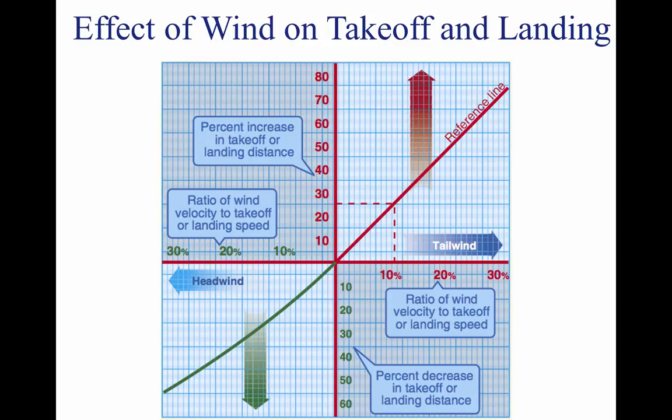The effect of pressure altitude and ambient temperature is to define density altitude and its effect on landing performance. An increase in density altitude increases the landing speed, but does not alter the net retarding force. Thus, the aircraft at altitude lands at the same indicated airspeed as at sea level, but because of the reduced density, the true airspeed is greater. The most critical conditions of landing performance are combinations of high gross weight, high density altitude, and unfavorable wind.